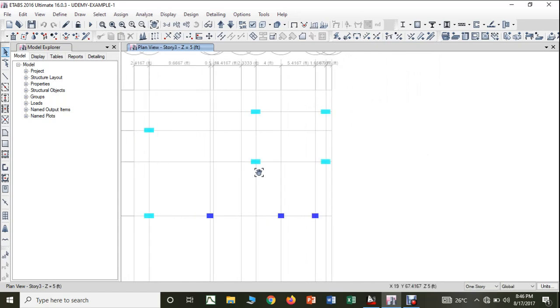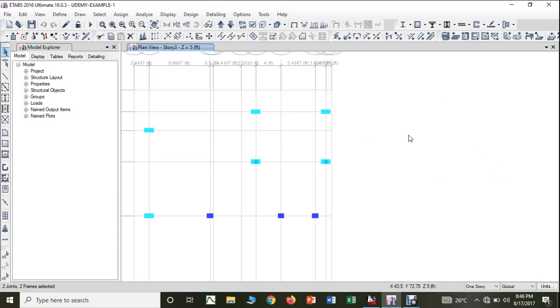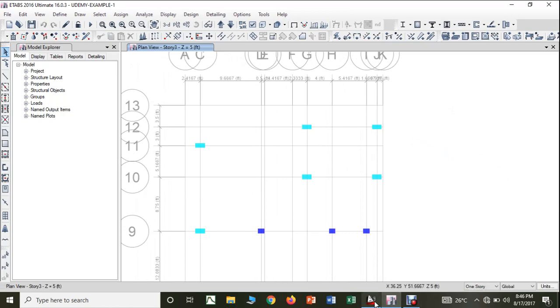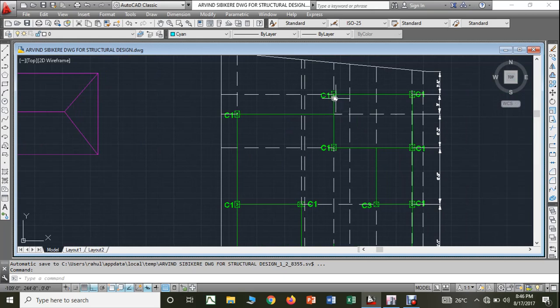I told you now I am not choosing the columns as per the dimension. Let us take the highest column and let us assign wherever the beams are required. Then later we will start modifying based on the span. Already we have the data. So based on that we will modify into the three groups of beams. Okay, right. So now I'll go to the plinth. This is my plinth beam. Now plinth beam means from here to here it is connected.